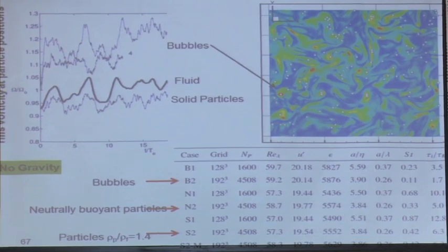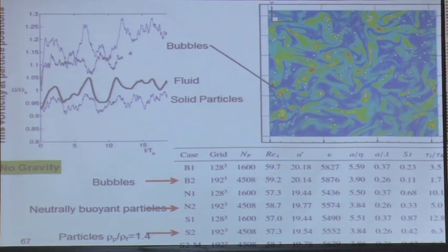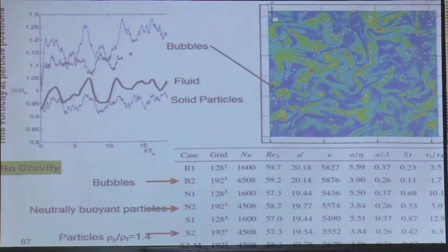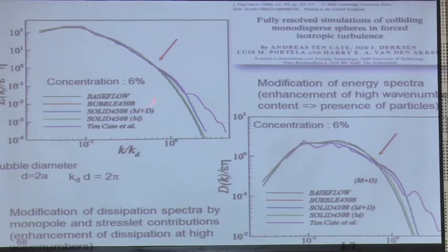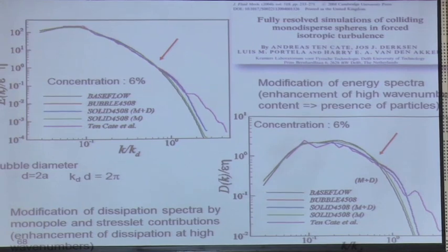You remember you have U prime V prime bar. So now I'm able to predict what U prime V prime bar will be for this suspension. And then I can feed a large-scale simulation with a k-epsilon model. But now I have fixed one of the key points of the modeling. Okay, so we looked at statistics and very complex things.